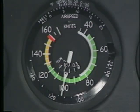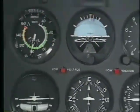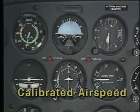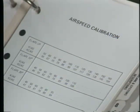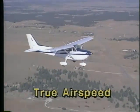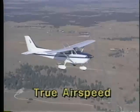During your flying, you will become familiar with several types of speed. For example, indicated airspeed is read directly from the instrument. However, when calculating airplane performance, you should use calibrated airspeed, which is indicated airspeed corrected for instrument and installation errors. You can determine calibrated airspeed by referring to the table provided in the pilot's operating handbook. True airspeed is your actual speed through the air. It is calibrated airspeed corrected for density changes due to altitude and non-standard temperatures.